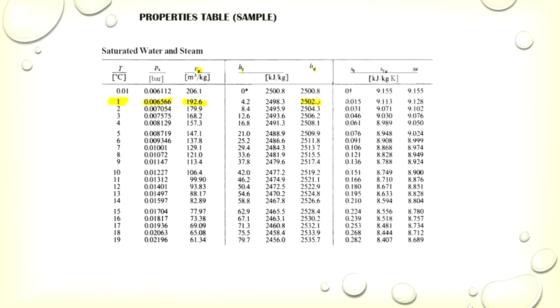So any h I give, if it is equal to this, then it's dry. Any h that is given to you in a problem that is less than that means it's wet. If it is wet, you have to find out the dryness fraction. If it is more than, then it's superheated. The same for entropy as well. If it is equal to this, then it's saturated liquid. If it is less than this, but more than this, always we take the g as comparison. So anything less than this is a mixture or wet vapor. Anything equal is dry. Anything more than is superheated.